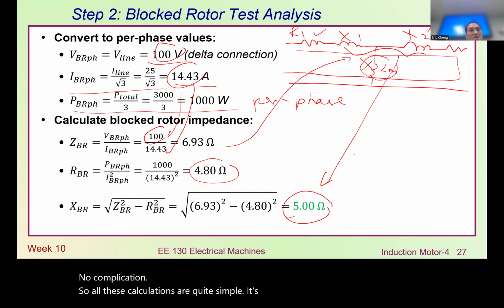Sometimes in block rotor tests, some engineers tend to use lower frequency too. At low frequency the losses become even lower, to be safer. However, for convenience, we may not be able to get other frequencies. You see our power point here is 50 or 60 Hertz. If you want to get something like 25 Hertz or 10 Hertz, it is quite complicated, impossible, unless we have an inverter. So that's why in some of the tests, we just use lower voltage but retain the same frequency.